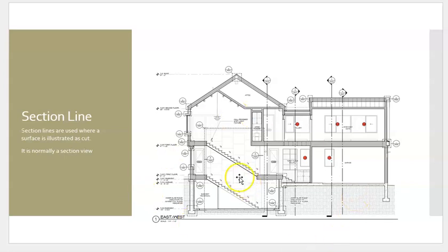So this is what I was talking about with the cutting plane. We cut that building vertically, and now we have section lines. And then you can see these cutting plane lines. So there's more detail representation. And here's that circle with the information of what page I could go to see more detail of even this cross section. This cross section is giving me so much detail. Here's a perfect example of the staircase, right? Stacked on top of each other.